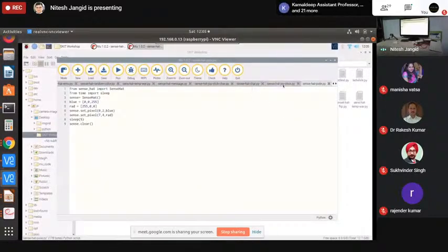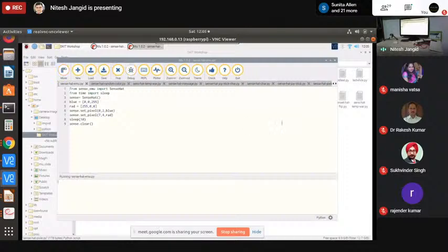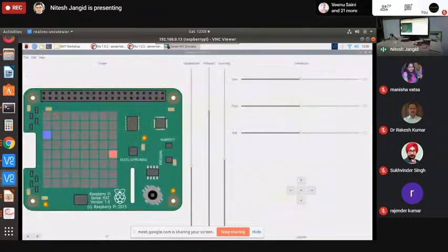So let's see the sense hat emulator. So here is sense hat EMU. I'm just going to run it and you see that you have emulator movement, and the corresponding pixels are bright with different colors. Okay, so this is a software application which emulates the complete behavior of the hardware of the sense hat. You need to just do one change, just import sense hat from the library sense EMU in place of sense hat. So here you will see all the effects that you want to achieve on the hardware. So this is a costlier way to interact with this hardware.